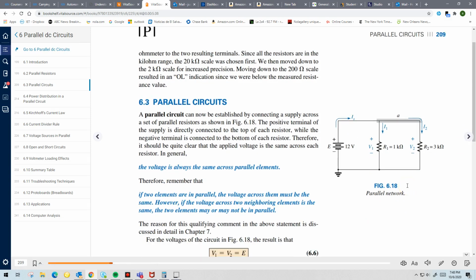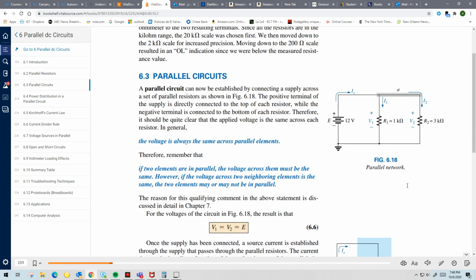All right, so now that we know how to combine resistors in parallel and how to manipulate them, we can then add a source, and then we have a circuit. So what's particular about parallel resistances, going back again as a reference with series resistance: remember, in a series connected circuit, the current remains the same, but the voltage splits. Well, in a parallel connected circuit, the voltage across the elements remains the same, but the current splits.